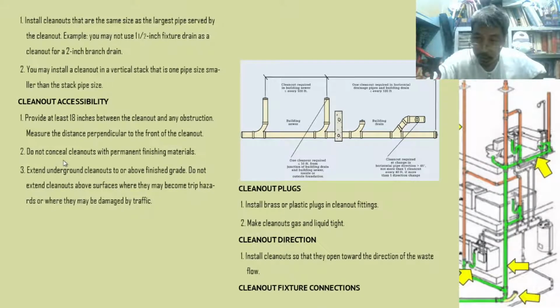Do not conceal. Extend underground cleanouts to or above finished grade. Do not extend cleanouts above surfaces where they may become a trip hazard, or where they may be damaged by traffic. This is very logical. Do not install a clean out where there is a provision for an access space. Place it on the other side, for example.